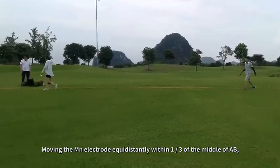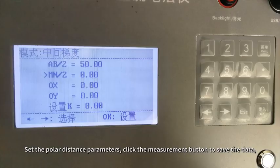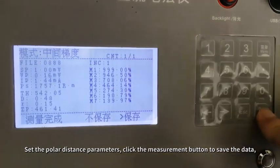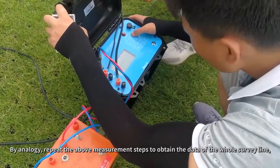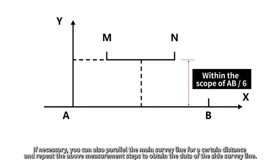Move the MN electrode equidistantly within 1/3 of the middle of AB. Set the polar distance parameters. Click the measurement button to save the data. By analogy, repeat the above measurement steps to obtain the data of the whole survey line. If necessary, you can also parallel the main survey line for a certain distance and repeat the above measurement steps to obtain the data of a side survey line.